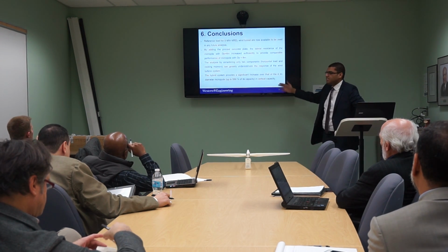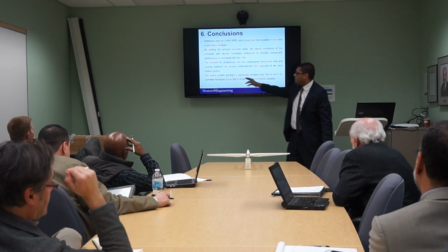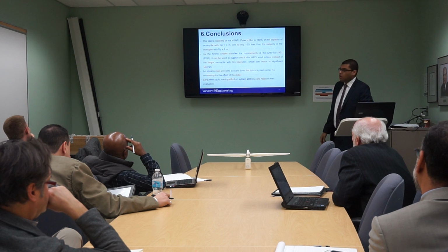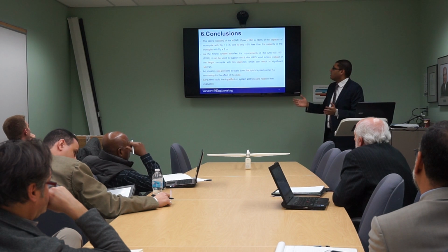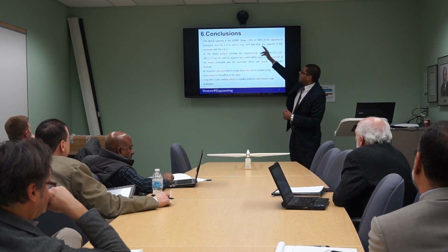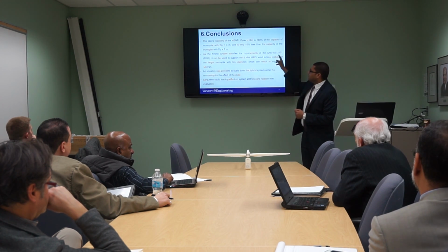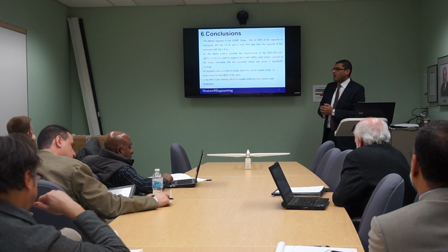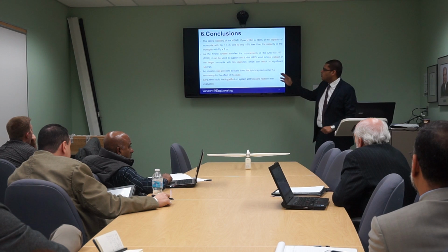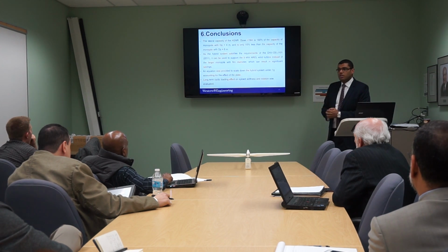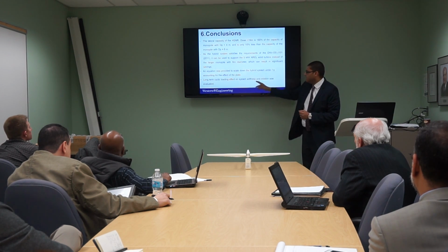We have seen the increase in hybrid capacity under the vertical capacity of the hybrid system. We can see also that although there is a difference between the lateral capacity of the monopile and the hybrid system, and the monopile with diameter 6 meter has larger capacity, the DNV requirement at rotation 0.5 is applied for both of them, so we can use the hybrid foundation system. We provided the equation to be able to scale down the model and to take the effect of the blade. We studied the long-term effect on the stiffness and the rotation.